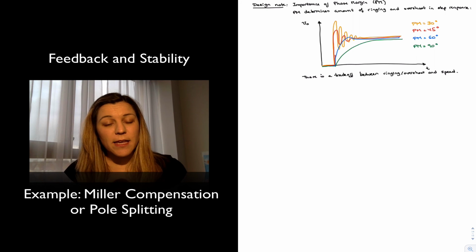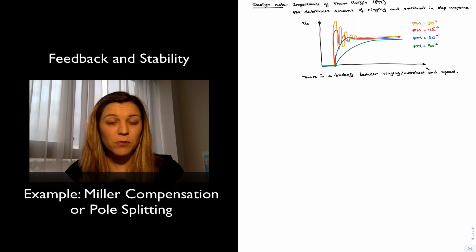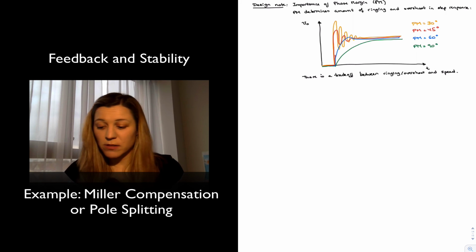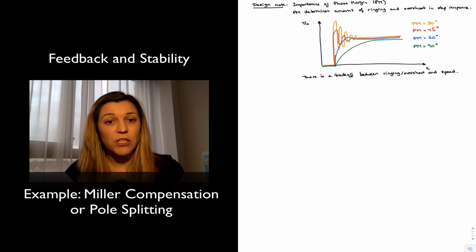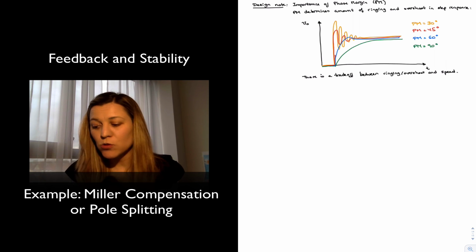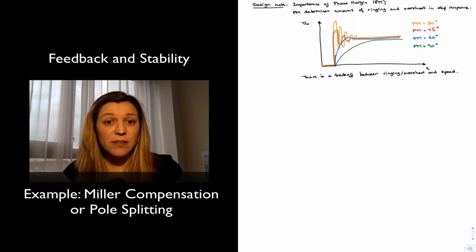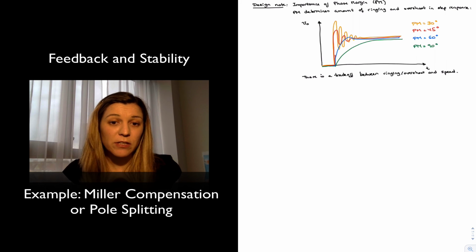Now, when that is the case, the datasheet will typically specify the range of gains for which the op-amp will be stable, as well as they'll typically provide some external connections. So in case you wanted to increase the amount of compensation for your particular application, you will just have to connect your capacitor externally. But those will be basically faster op-amps. Why would you want a compensated op-amp instead of a decompensated one?